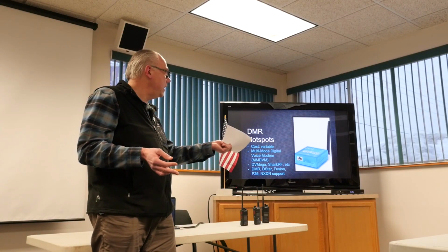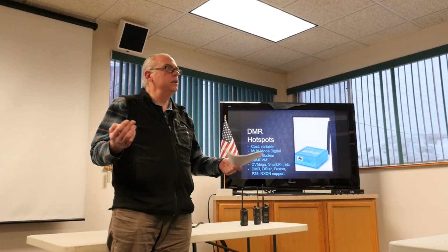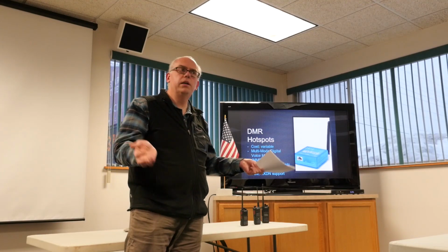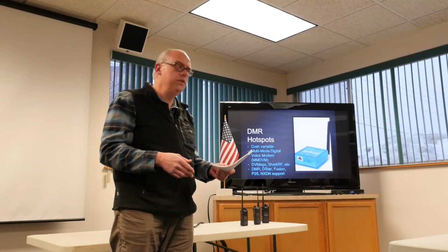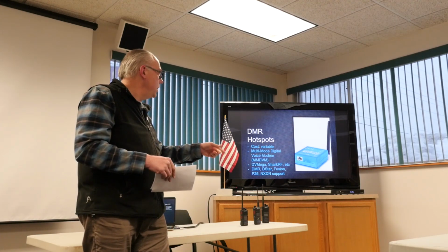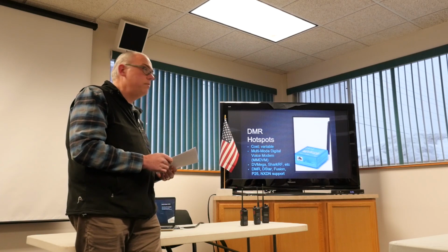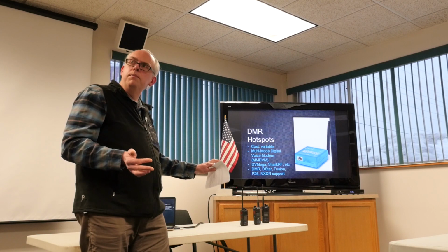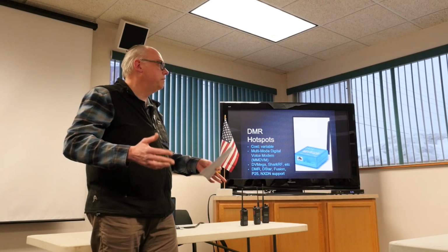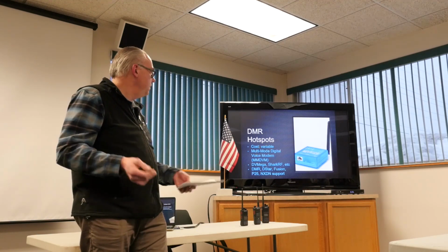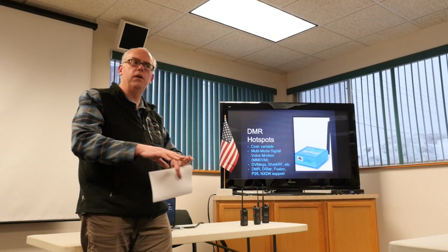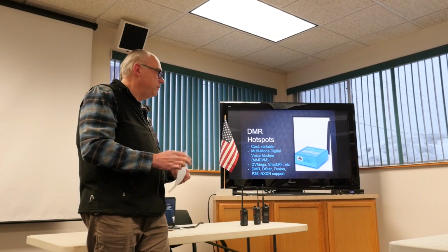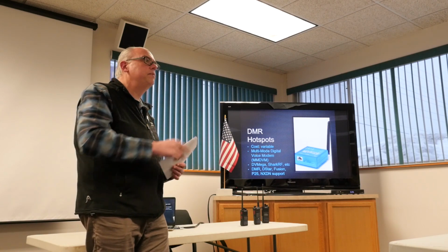So I've got a hotspot in my house, and I can talk to the Wisconsin talk group. I can talk to Nationwide. I can dial in any ones that I choose. And these hotspots actually are multi-mode, so they'll work with DMR, D-Star, Fusion, P25, NXDN. All of those digital voice modes you can use with your hotspot. You just have to alter the programming a little bit.